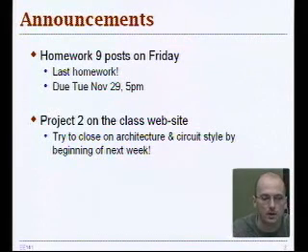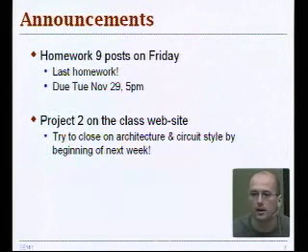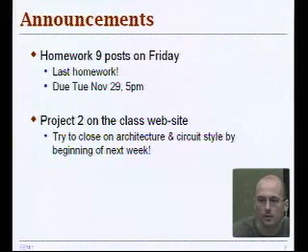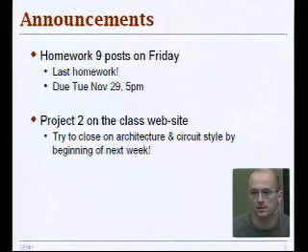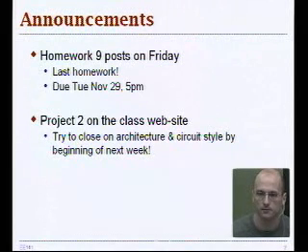Since your goal is to minimize the delay of your design, it would be fair to keep the clock phase equal to the critical path, maybe a little bit longer, and have a 50% duty cycle. So in that case you can't have a really sloppy pull up and then a really fast pull down. Pre-charge cannot be really sloppy. That's what I'm trying to enforce here. So basically, clock frequency would be critical path plus epsilon, and that's going to be half of your clock period, pre-charge and evaluate. Make sense?